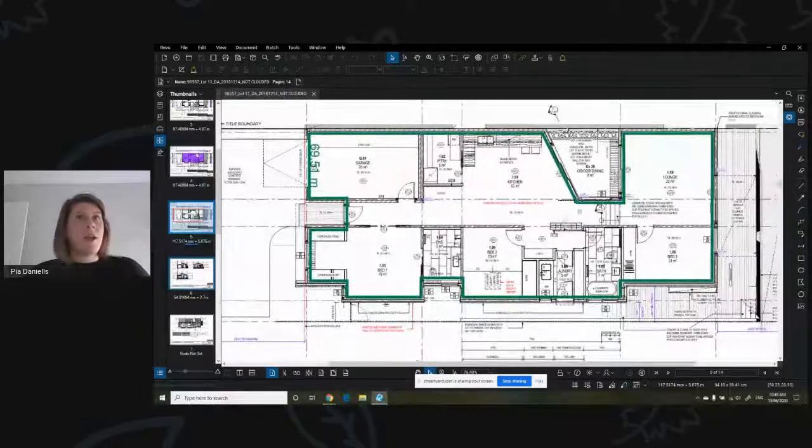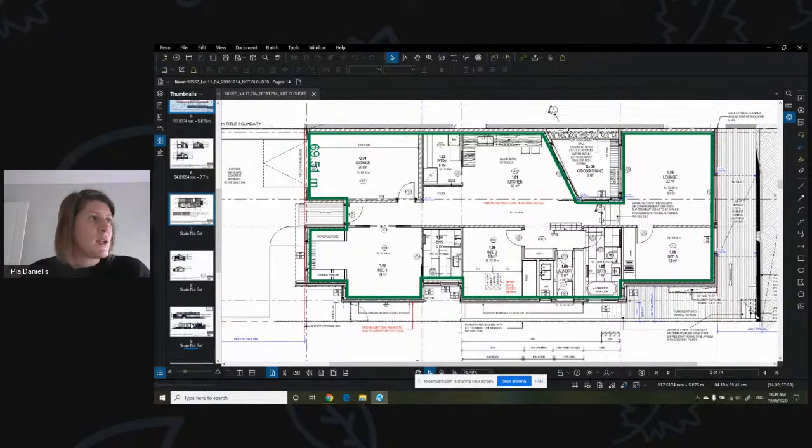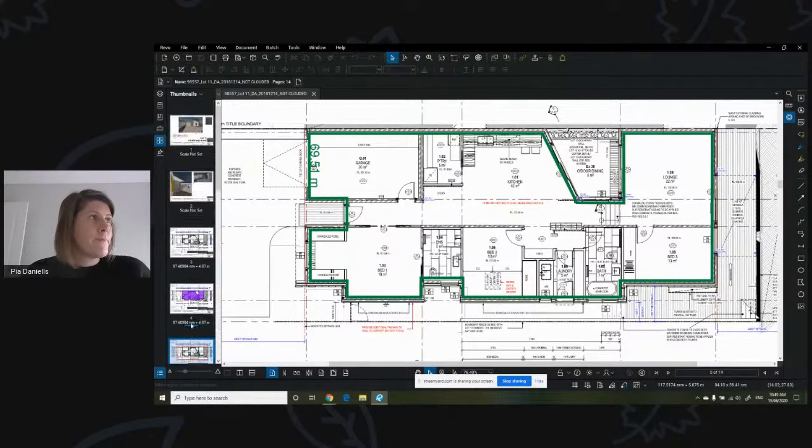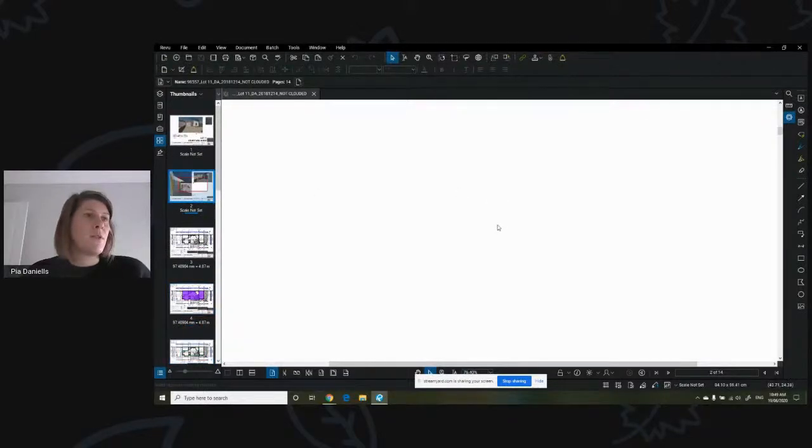Now this building has a pergola running along the eastern side of the building, has a small shade over some of the western windows, and no shading along the south, which is because it's not necessarily needed. And really only the northern window here has vertical shading to it, which can be seen here in one of the perspectives.